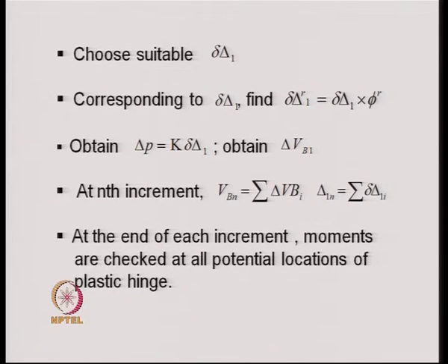At any time, say at the nth increment of the load, the total load is equal to the summation of delta P over the n increments. Similarly, the base shear can be calculated by summing up the base shear for each increment of loading up to the nth increment.